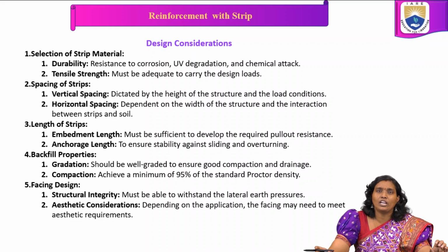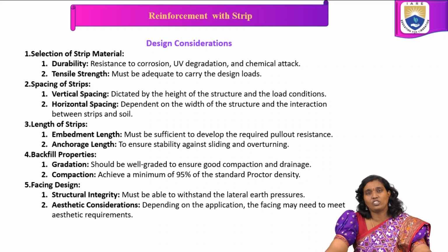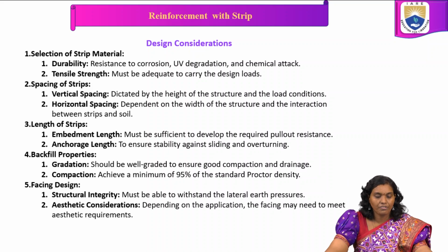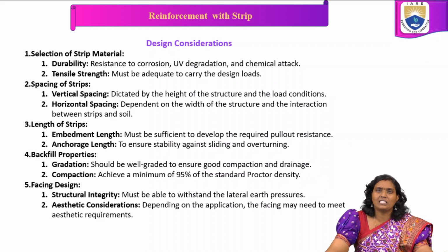It depends upon the durability and tensile strength properties. Durability means resistance to corrosion, UV degradation and chemical attack, so that the material is durable. And the tensile strength must be adequate to carry the design loads.